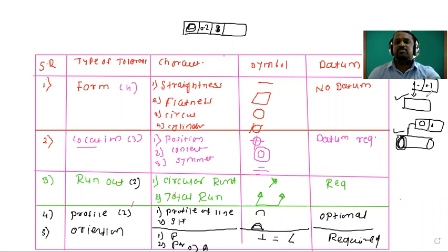For this purpose we have developed the geometrical tolerances. With the help of the geometrical tolerances we can easily understand, suppose we have to manufacture these surfaces. Suppose we have to manufacture this component, and during manufacturing, if your straightness or your flatness or your circularity varies, that variation should be in the proper tolerance zone.